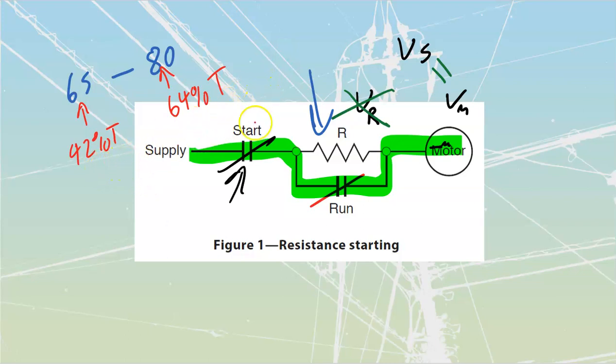So if my startup torque was 300%, the design D, 300%, I would take that 300% and just multiply it by whichever one of these I was using, and that would tell me what my actual startup would be off of it. Because otherwise it would be a phenomenally large jump in torque that we would see, where we're going to start, and then all of a sudden this motor kind of goes up like that.